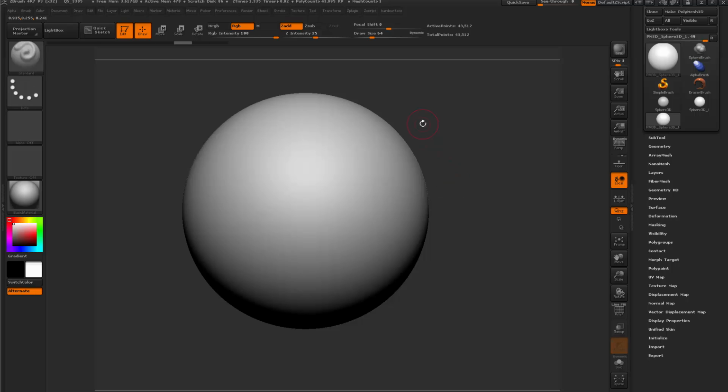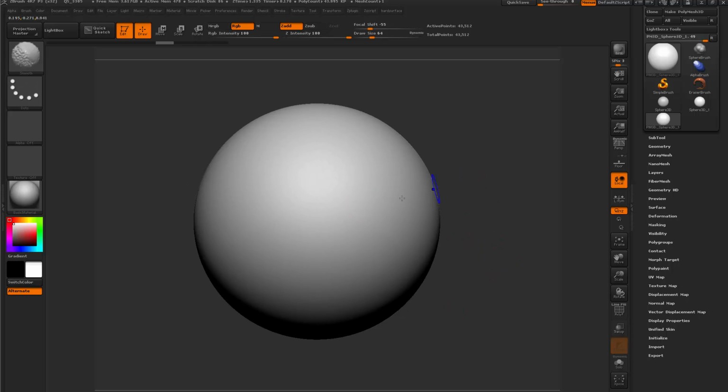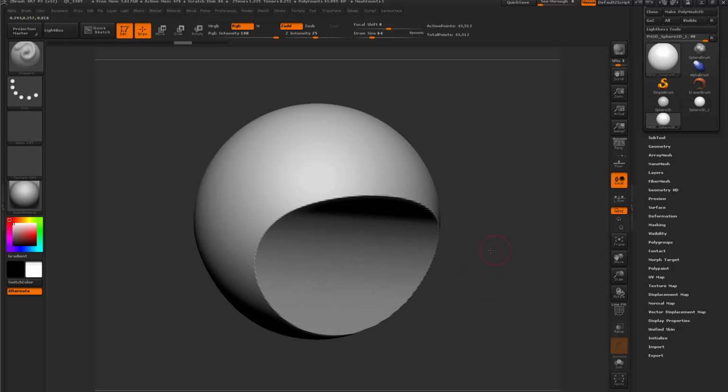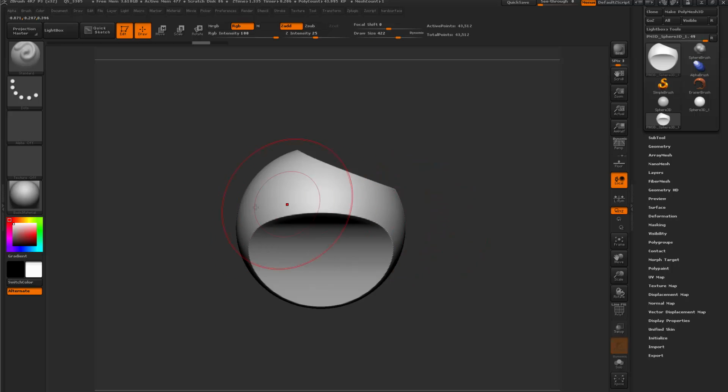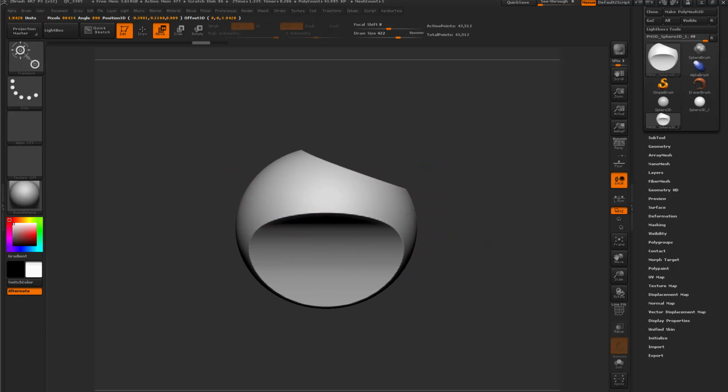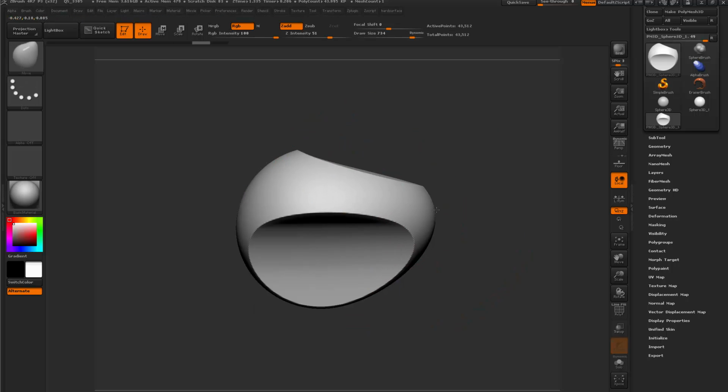And then you can also change the direction of cutting by holding down Alt before you release the left mouse button. That's all you can do with the Clip Curve. So let me go Control Shift and then create a nice and smooth curve to cut out the bottom. And maybe I can have a steeper face on the top. And maybe I can make this guy longer. Or I can just drag the bottom back.